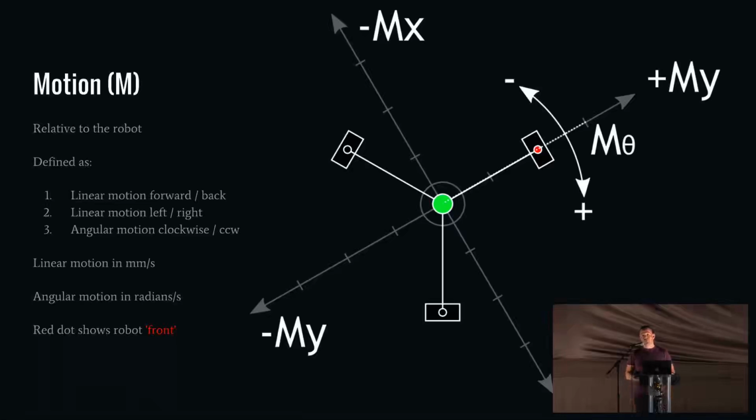So the first thing we have to sort out are coordinate systems. There are two frames of reference in this environment. There's the world frame, so if you're standing there driving your robot around, you have a notion of forwards, backwards, left and right relative to you. And there's the robot's coordinate space, which moves around with the robot. You'd encounter this typically if you drive a remote-controlled vehicle around. When you turn left, it turns left as far as it's concerned, not as far as you're concerned. So if it's driving towards you, it'll actually turn right. So we define a motion